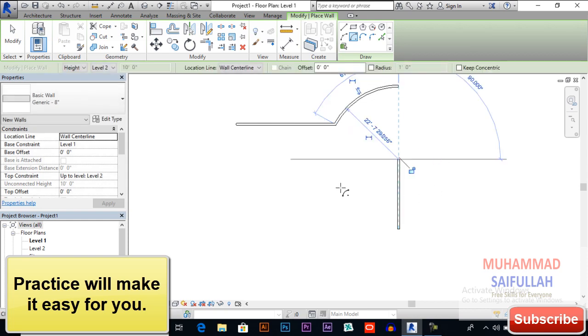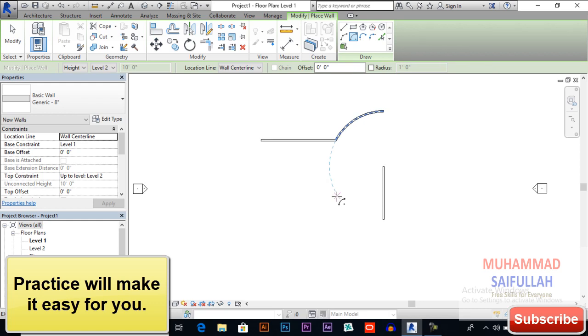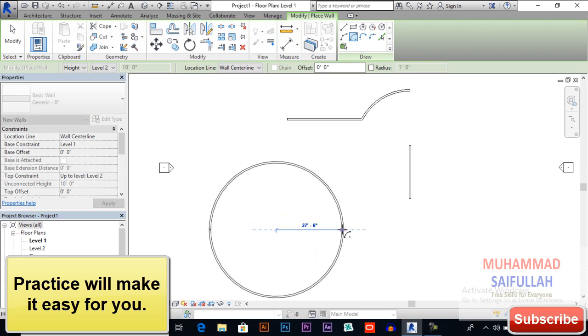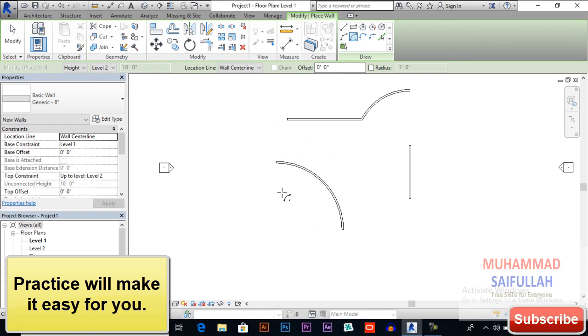So that's how you can create an arced line. You also can draw from this side. First you draw a circle, then start point, and then end point. That's how you can create an arced line.